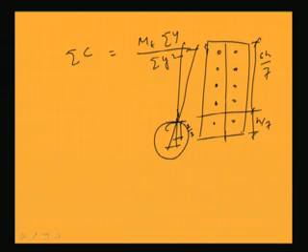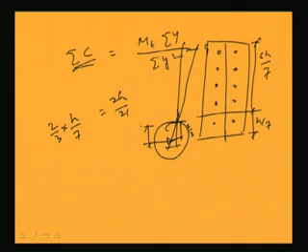That means, this compressive force, this one, total C, will act at a distance of 2/3 of h by 7, that means 2h by 21. So, this distance will basically be 2h by 21, at which the total compressive force will act.